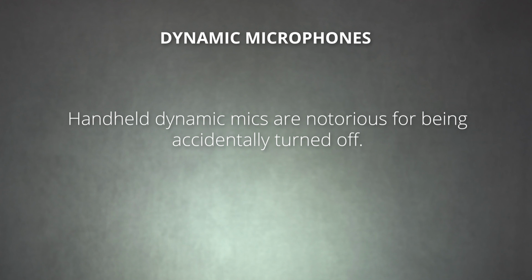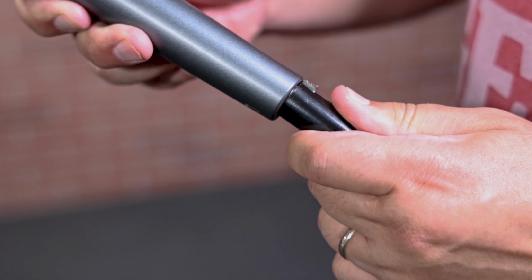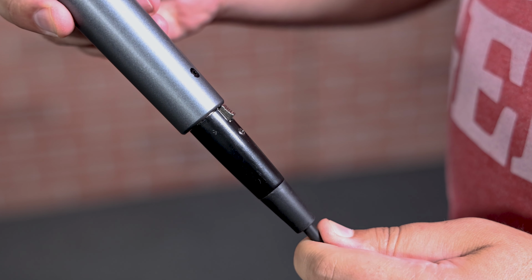Another common problem you might encounter is that there's no signal or no input. Handheld dynamic mics are notorious for being accidentally turned off. If the mic has a mute or on-off switch, check that first. It's likely to be the issue. If the problem continues and is not the mute or on-off switch, check to make sure the cable is properly connected to the mic and its output destination.